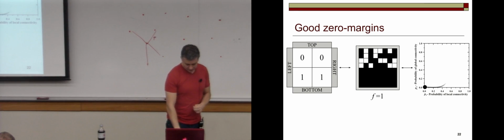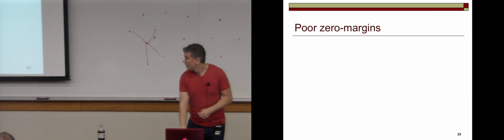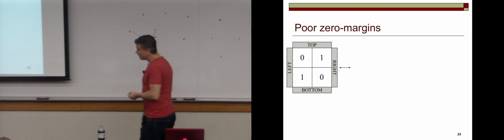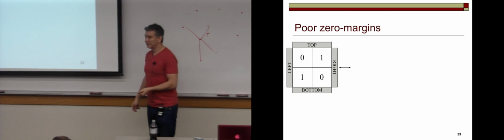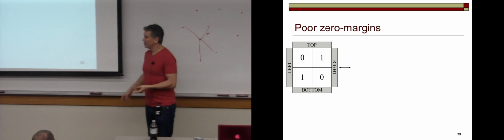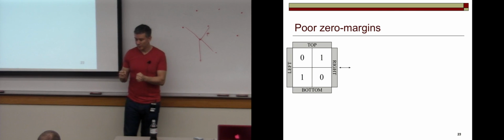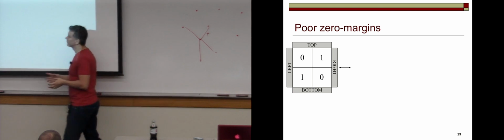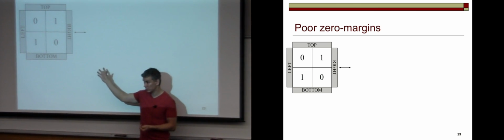But the pathological case, or the case where things go bad, is in the case of the possibility of sneak paths. The asymmetry here has to do with the fact that we have 4-connected switches, so we have switches that have 4 connections. We will not get top-to-bottom connectivity across a diagonal. So if we were to lay out our function like this at the macro level, the function should evaluate to 0. Does everybody see that?